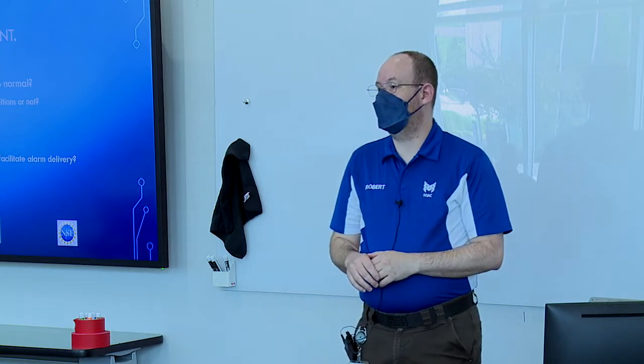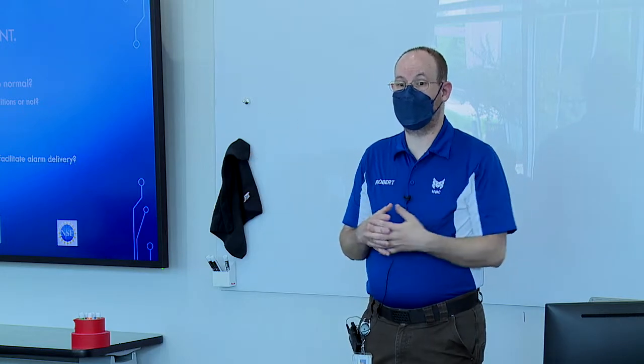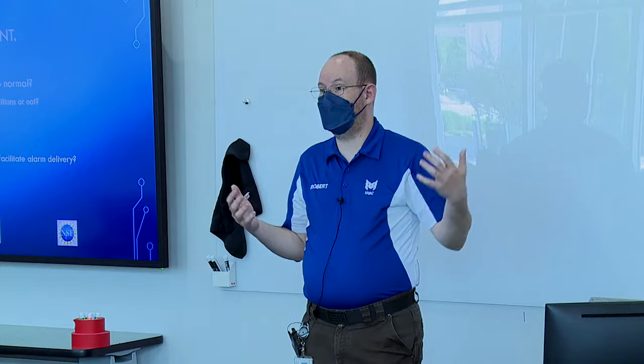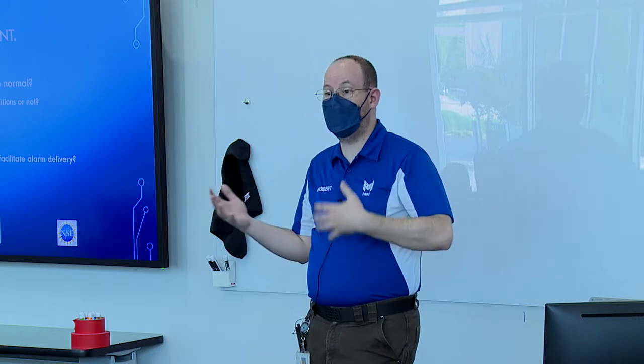Okay? Maybe one of those alarms isn't actually useful to the building because it doesn't apply to this piece of equipment really. Instead of a fixed discharge air set point, it's a variable set point. So trying to alarm off of that may be challenging. And it may miss a whole stack of alarms because this piece of equipment got added later on and didn't catch that part of the spec for update.